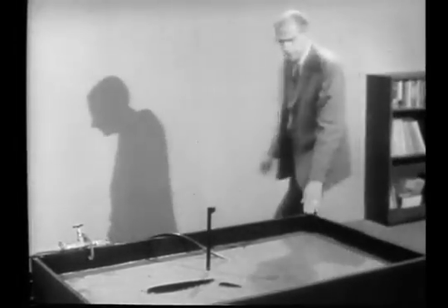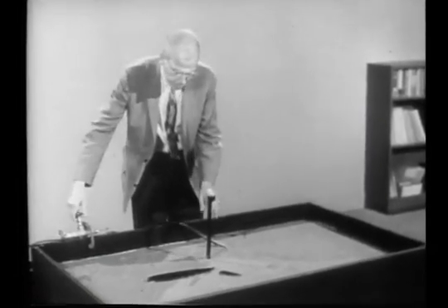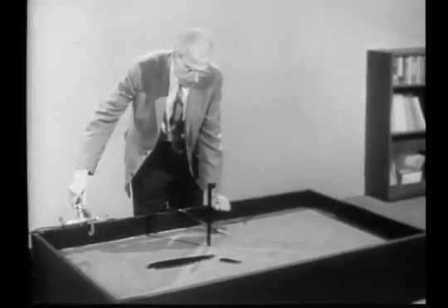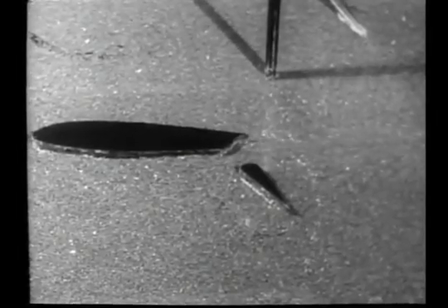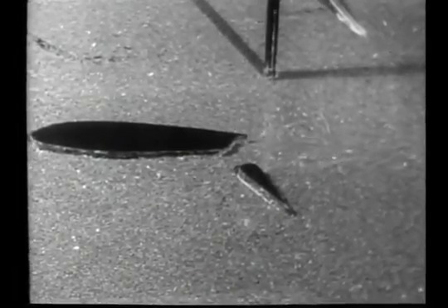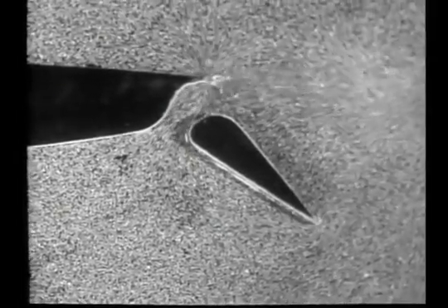Still greater effectiveness can be obtained from blowing jets if they are produced by the direct application of power rather than by the limited differentials available on the body itself. The jet, moving at high speed through the surrounding fluid, creates regions of high viscous stress at its edges, and as a consequence drags substantial amounts of fluid along with it.